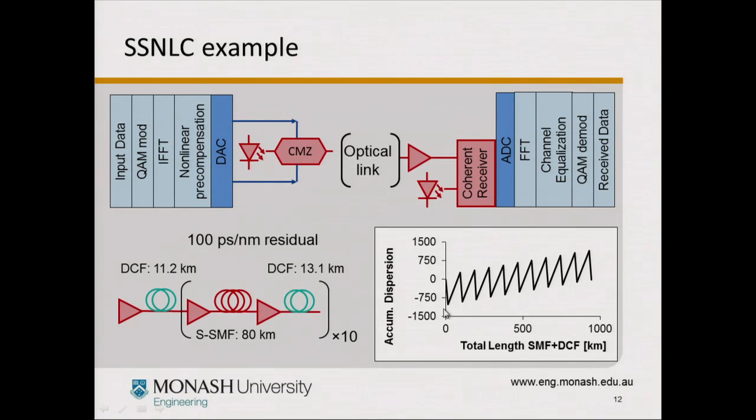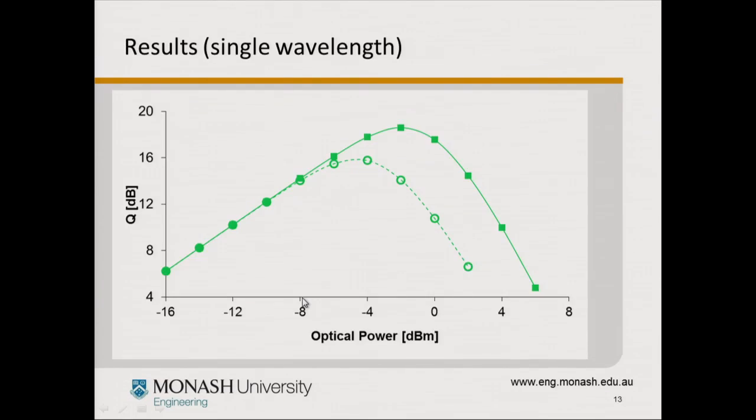Okay, so to quantify the benefit that you can get, we can use numerical simulations, for example, where the optical link is simulated in a very elaborate method, with very short steps to guarantee us good accuracy, and the compensation methods are done with this very coarse single-step method. So there's the link there. It's a typical dispersion compensated link, an 800-kilometer link with some dispersion pre-compensation, and then a typical link with some residual dispersion per span.